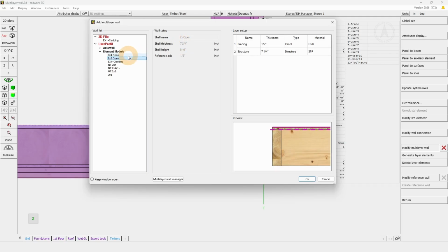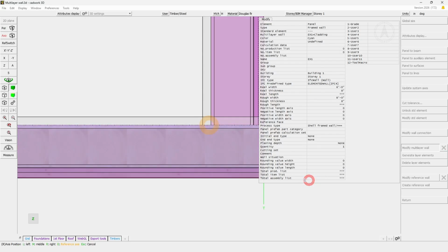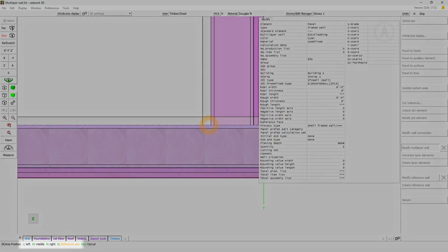Here the thing is, when I'm replacing a wall by another, what is always true is that one of the main points of the wall will remain at the same location. It can be the inside of the shell, the outside of the shell, the middle of the shell, or the reference axis. In our case, this is what we have in common between these two walls, and this is what we should base our change on. So I'm simply selecting the new one, pressing OK. And now at the bottom of the screen we have the 4 options previously described available.